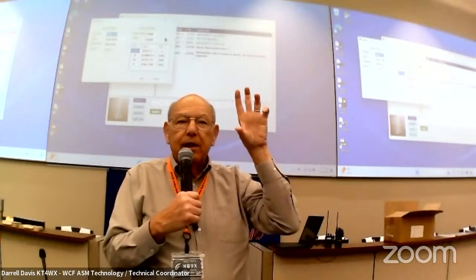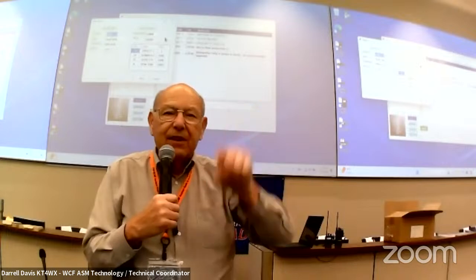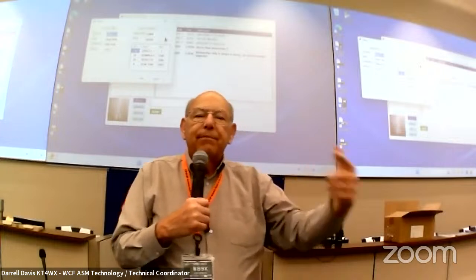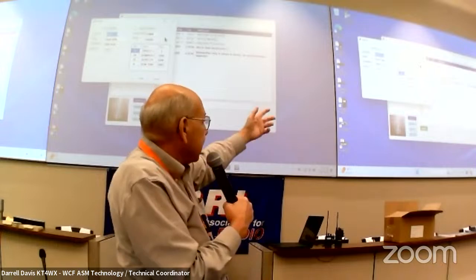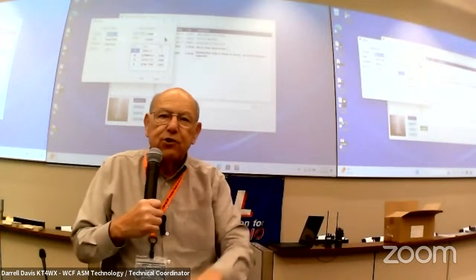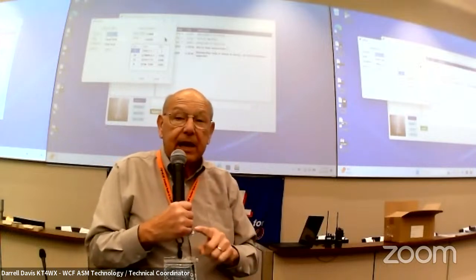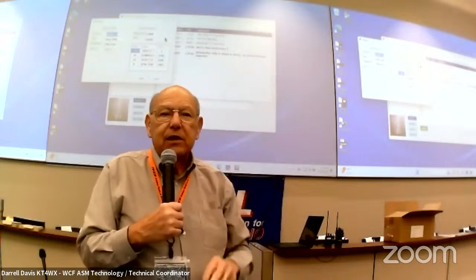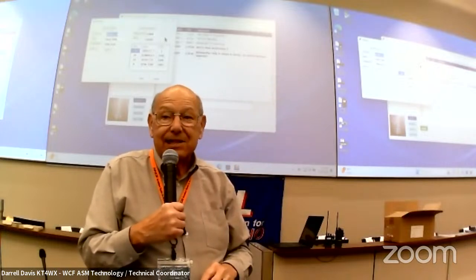When you're counting up the number of memory channels to finally figure out what channel number that memory channel in zone 4 needs to be, you've got to include the other 2 channels that have nothing in them. Because as far as the radio is concerned, they're still allocated. So in this case, that's how we got to 24 and 23. And if we only had 15 channels in that first zone, but there were 16 allocated, zone 1's numeric factor would be 16.